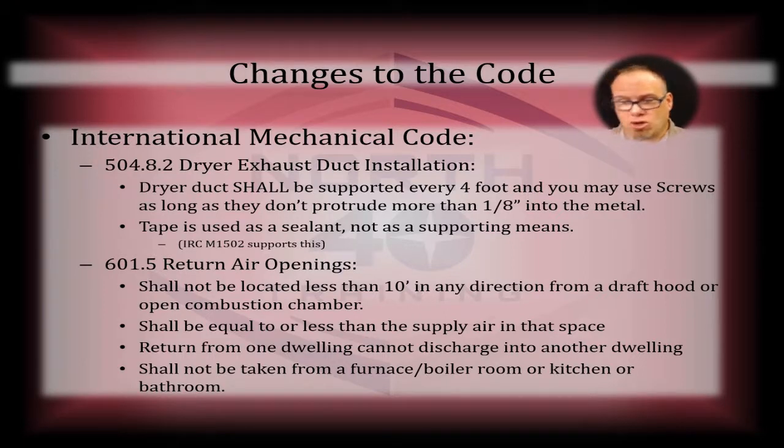Now, why? So we can churn that air. We're supplying heated, cooled, dehumidified air to that room. We're drawing out the stale air that's been in there, mixing with everything else. And so we're keeping that churning, which is healthier for people, and it also will create less hot and cold pockets.